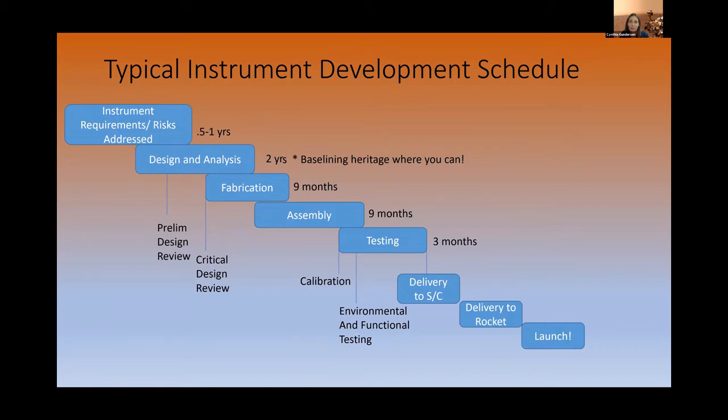It's super important to use vetted and high-quality machine shops, as there is rarely schedule to absorb bad parts. Once parts are in, they are kitted for each subassembly for the highly skilled assembler to work their magic. And I can't tell you enough how critical it is to have the right tech team working on these instruments, and technicians that stay to work on the next instrument. Mass spectrometers are some of the toughest spaceflight instruments just from the sheer number of parts required for it to work.